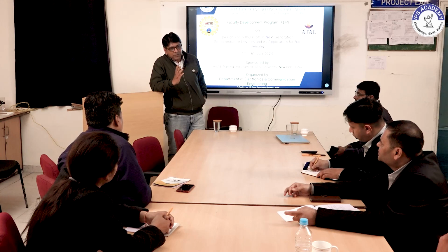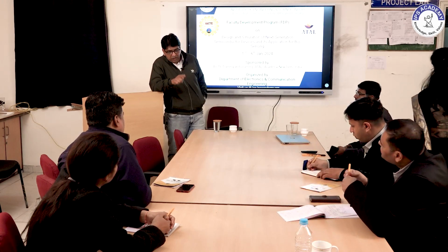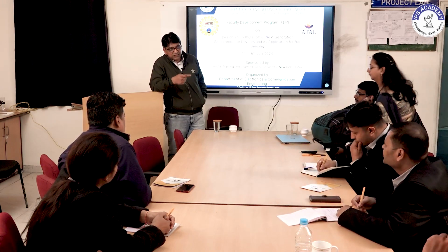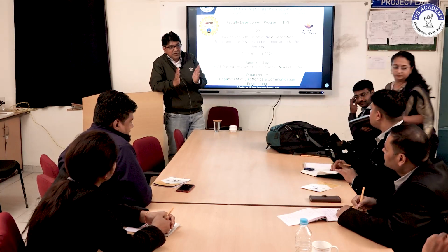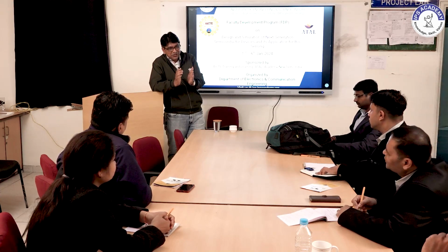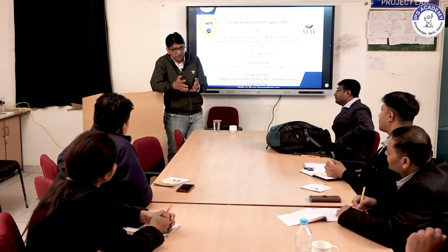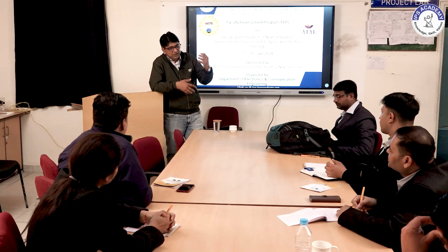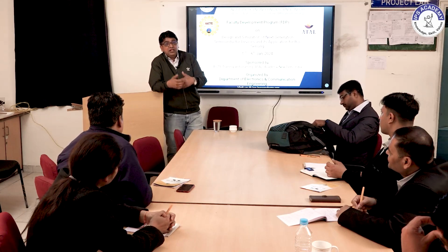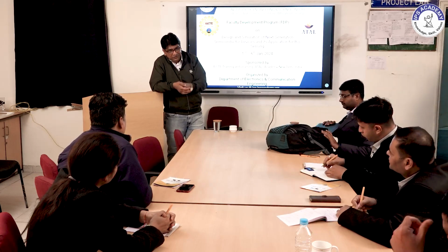And the drawback for the upper device, meaning the higher node, is that capacitance is the big issue, because around the channel we can put the gate oxide. Capacitance will definitely affect performance in terms of delay. But another advantage is that we scaled down the transistor, so source and drain will come very close, so the speed will enhance. Getting my point? So some trade-off is there. Somewhere we have the capacitance, but we also increase the current, and also improve the gate controllability. Got it?